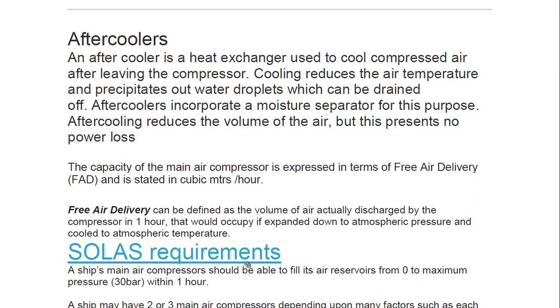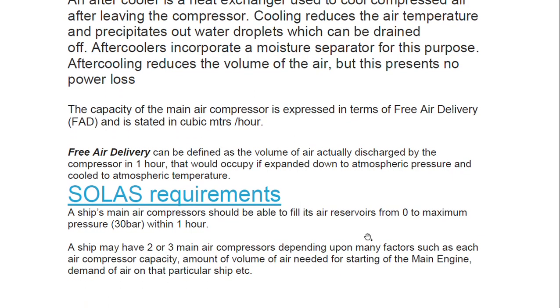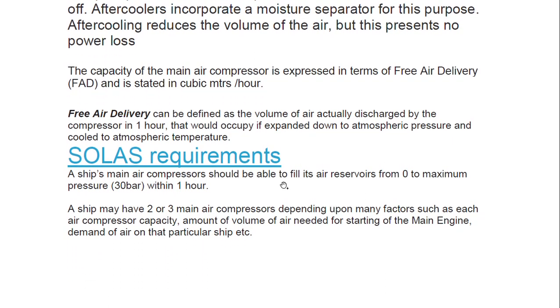Okay, now when we talk about SOLAS requirement, for air compressor we have a SOLAS requirement that a ship's main air compressor should be able to fill its reservoirs from 0 to maximum pressure 30 bar within 1 hour.